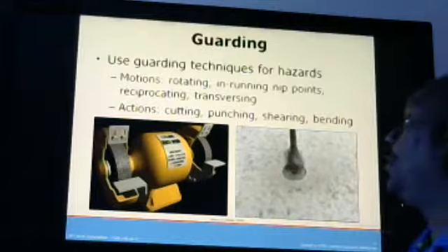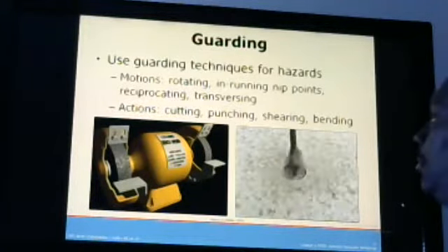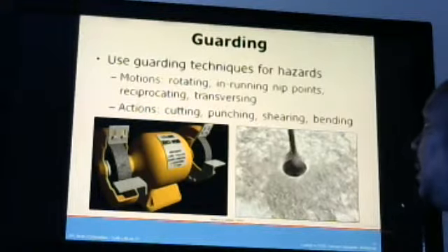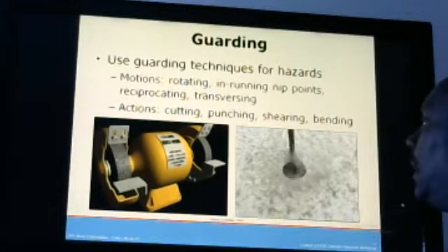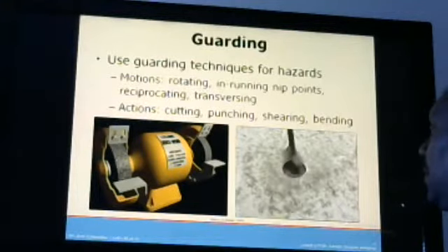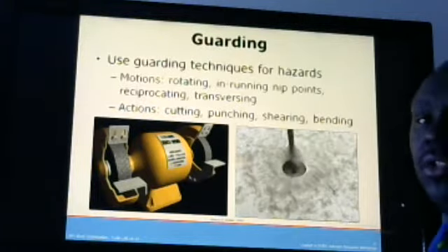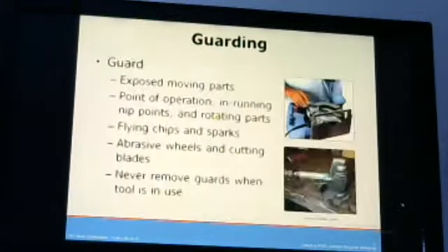So you see we got the tools here. When using the tools, you have motion and rotation, running nip points, reciprocating and transverse actions, cutting, punching, and shearing. You see these tools here. Make sure that the right guard is on the tools and they're used in the right fashion.